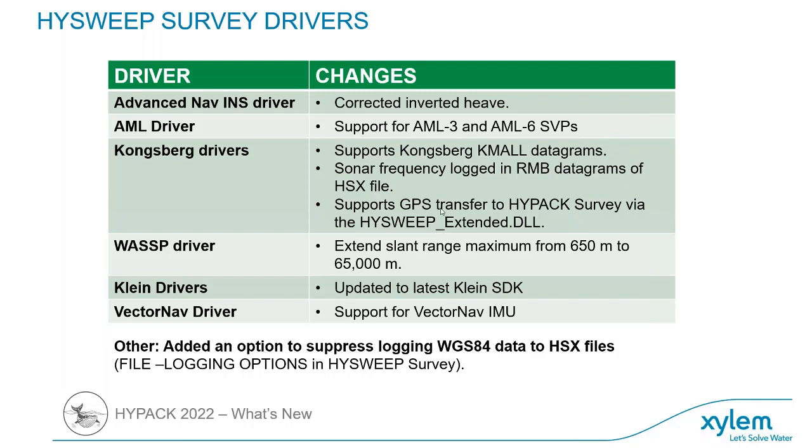A few other things. We actually have a GPS transfer option. So if you're running SIS in the background or whatever, and all the position and everything is being imported into there, we can just take that datagram and pass it on to HYPACK survey. Some changes to the WASP driver. The Klein drivers have been updated to the latest SDK, and then also the VectorNav driver is available in HYSWEEP as well.